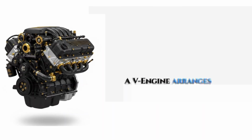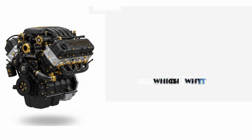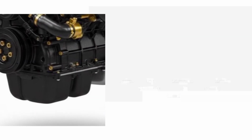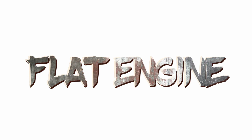A V engine arranges its cylinders in two separate rows that form a V shape when viewed from the front. This layout allows more cylinders to fit into a shorter space, which is why it is commonly used in larger and more powerful cars. V6 and V8 engines are especially well known for delivering strong performance and smooth power. Over time, this design became a favorite for sports cars, trucks, and luxury vehicles because it provides a good balance between size and power output.